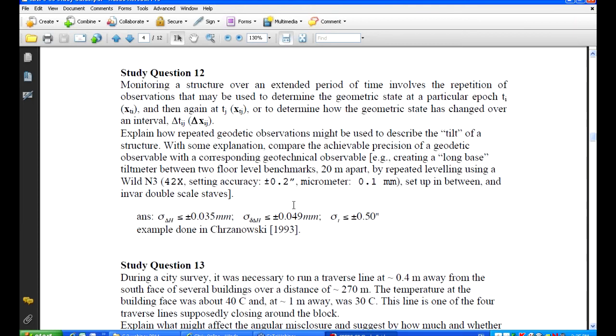And the advantage in this is that when we look at the calculation of delta delta H divided by S, the uncertainty in the horizontal distance can be quite large. We don't have to know that all that well because of the way the propagation works. Same as with the extensometer and knowing the actual distance between the two anchor points. It's the same type of propagation.